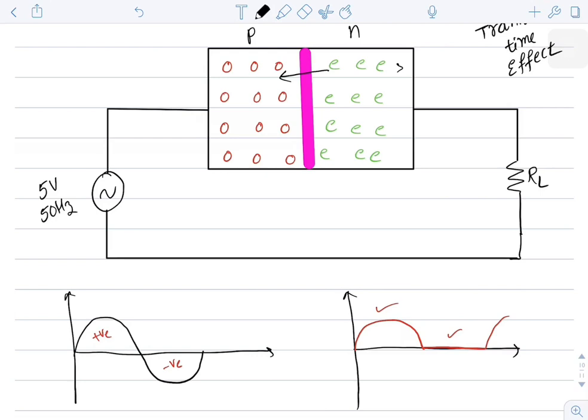Once the voltage is greater than the barrier voltage, the electron will move towards P-type material. Similarly, the hole will move towards N-type material. Let us say an electron which is available here is moving towards P-type region into a hole. Let us say this is the length of the material, that is L. If the electron is moving with a velocity equal to v,